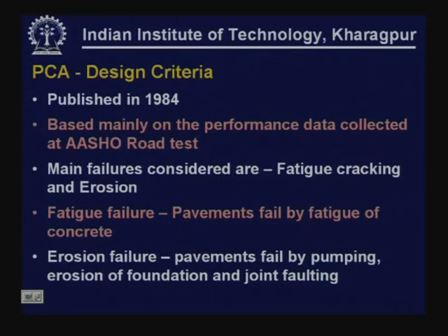The main failures considered in the PCA design procedure are fatigue cracking of concrete and erosion of foundation. So these are the two main failures. If you recollect, in the previous lesson on design of concrete pavements as per the IRC procedure, there also we made a mention of erosion failure, but IRC does not make any specific design provisions for carrying out erosion analysis.